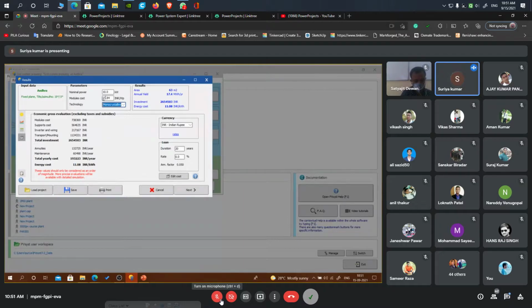This is about your preliminary design. And what you can get as output from this preliminary design means I can generate this much energy with respect to this much area, and I'm going to have this much capacity by using monocrystalline panels for Andhra, wherever I have chosen the location. In that place, if I am keeping the tilt angle as 19, this is going to be the result. This is what you can get from this preliminary design, right?